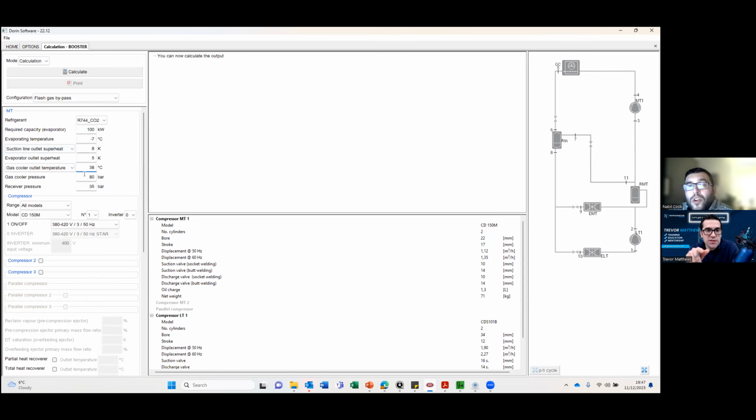So Nabil, just a second. So that evaporator outlet superheat, would it be plus the 8K? So 5 plus 8, that's actually what the compressor is going to see, 13K coming back? No. No, it's 8. Okay. 5 from the evaporator plus 3 from the suction line gives a total of 8. Okay, a total of 8 into the compressor.